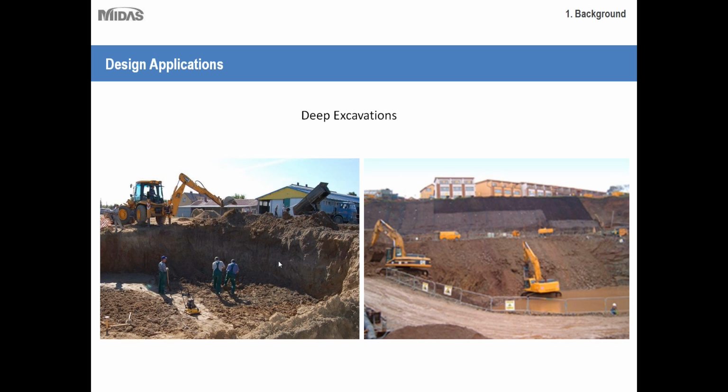So if you look to the left here, the shallow excavation, there isn't really much of a slope at all. It's almost a 90-degree angle. So why is that? The reason is just because the excavation is so shallow that it's negligible. I mean, you could still have a 90-degree angle such as this, and it would still be relatively safe to walk along the perimeter here. You don't really have to worry about it failing.